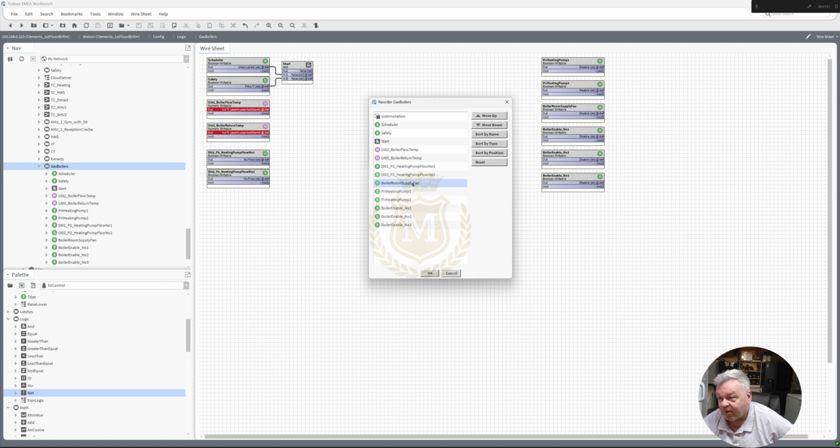And probably in order: boiler supply fan, prove running, primary heating pump 1, 2. Mind you, we don't need the boiler supply fan to run the pumps. But we certainly do need it to run the boiler. So that's basically the order: primary pumps, boiler supply fans, proved running. And I don't have a proof, do I? Because that's just an output. I don't know whether that boiler fan is running or not. I have no flow switch. I have no pitot with a DP sensor.